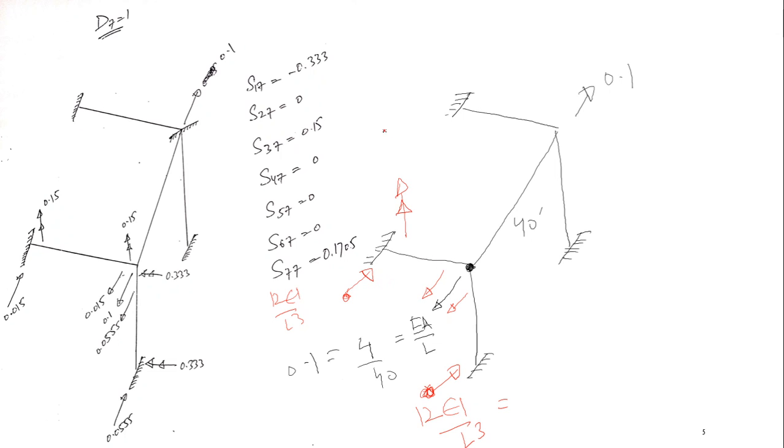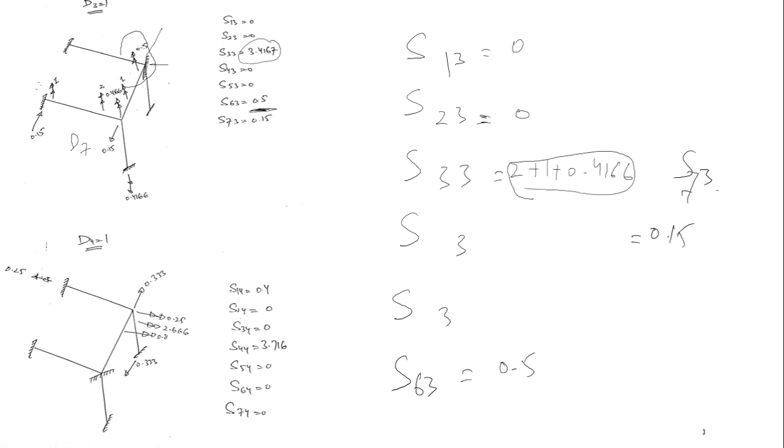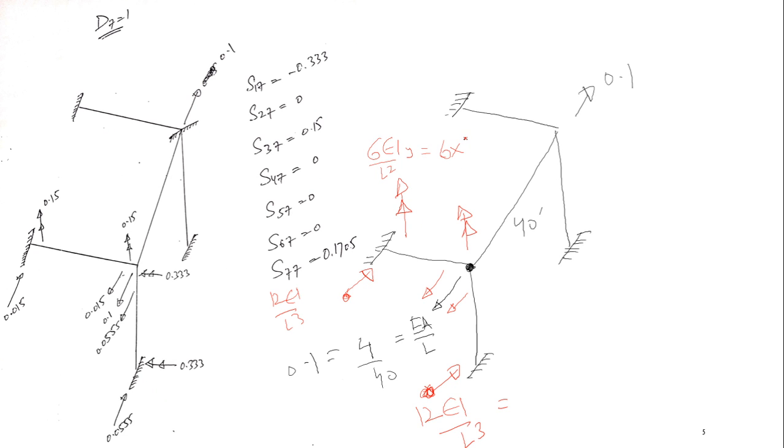This is in y. Its magnitude is equal to 6EI/L². So this is y, because this moment is in y. Similarly, this is forming a clockwise moment here. Resistive would be anti-clockwise here, and its magnitude would be the same as this. So 6EIy, EIy is 10. So 6 into 10 divided by length, 20 square, so it comes out to be 60 by 20 square, which is 0.15. So it is 0.15, and it's written here.